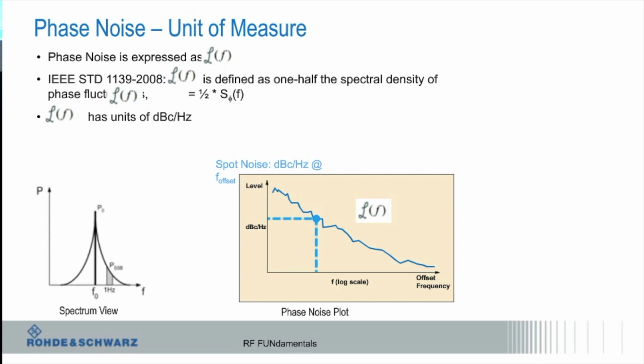Well, it's not really so much that it would be 10 hertz away. If I had a 10 megahertz tone here, the point is it's designed to be 10 megahertz, so the main energy is going to be at 10 megahertz. And if you look at it, that's going to go much higher than these curves. But they are there. So what you're really measuring is how imperfect is it from 10 megahertz? How much energy does it create other than at 10 megahertz? But you're trying to measure the energy that's not at 10 megahertz, right?